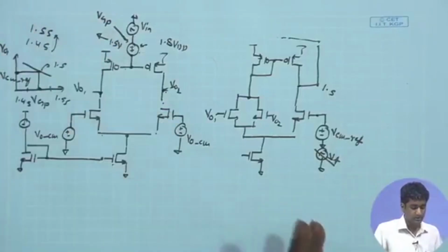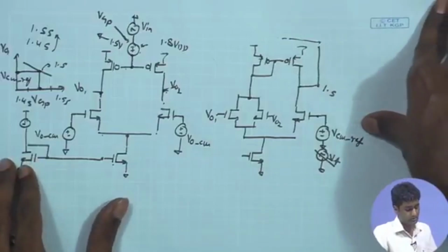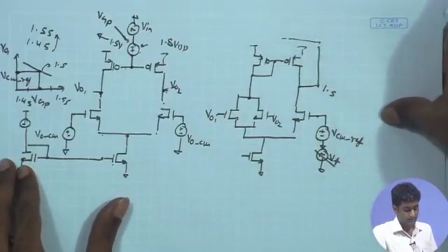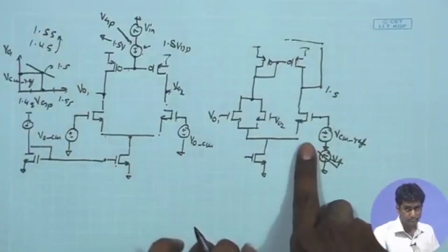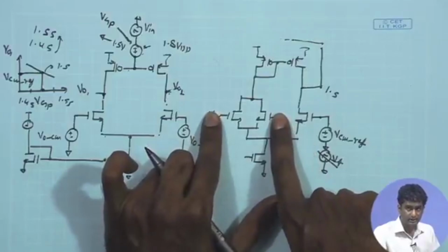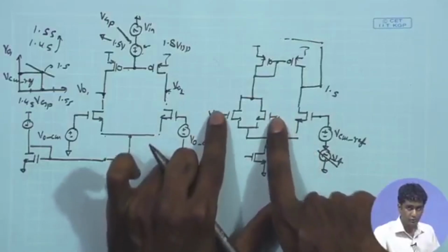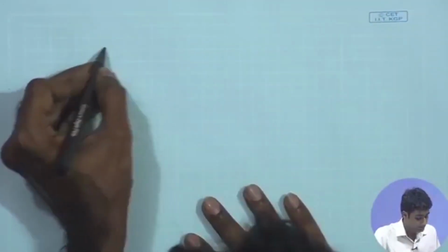So, let me talk about the other alternative that we also need to see. Some of you have tried the other way, in which the loop can be opened at this point. So, once again similar considerations. If I am opening the loop at the input point, there also we just need to make sure that the overall DC condition is maintained.